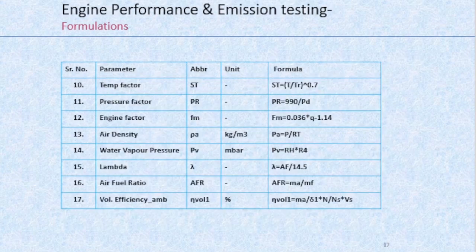Even though the corrected power is not a part of emission calculation, towards comparison purposes of equivalent engines and declaration of power at standard reference conditions, the correction factor is calculated. As described earlier, serial 10 and 11 form the atmospheric factor and serial number 12 is the engine factor. Depending upon the application, the correction factor formula changes with respect to indices of values A and B.